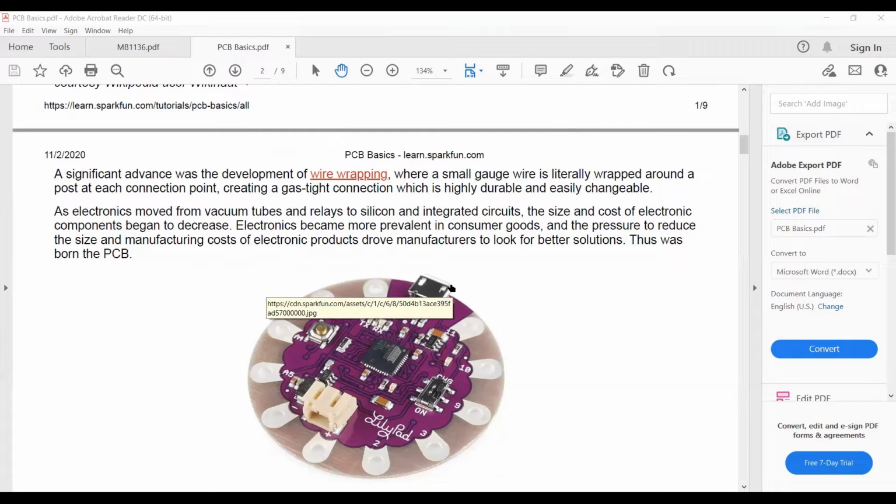Say example, in 2000 people used PCB as big boards. Computers were very big, correct, right? Now computers have come down to mobile phone size, tablets and other stuff. Yes, ma'am. Now say example, relays: why are we using relays? We use them for switching the NO/NC connection, for example to switch on a light, for high current only. Nowadays, if you want to switch for low current or low voltage, use a transistor, correct?